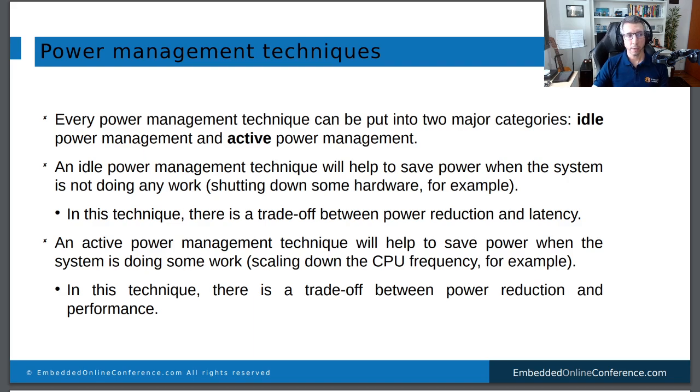If a hardware is idle, you can turn off the hardware, and as a result, you save power. In idle power management techniques, we have a trade-off between power consumption and latency, because we have wake-up times, the latency to wake up a piece of hardware.